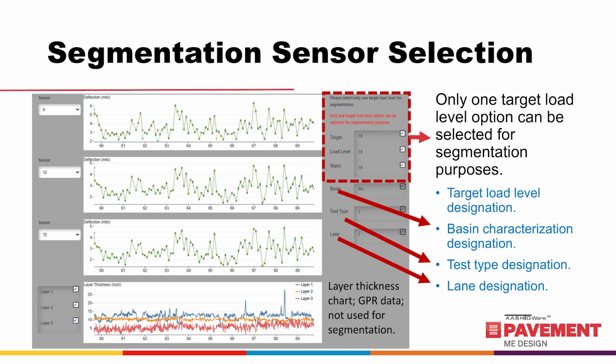If the project includes a typical and Type 2 basin, both or only one can be used for the segmentation. It is suggested that the user keep each of the basin types checked while the others are unchecked to determine how many of the deflection basins are within each group or basin type. If a substantial number of the total are a Type 1 and/or Type 3, the entire FWD file may need to be reviewed to determine the reason because those data points will be removed from back calculation.